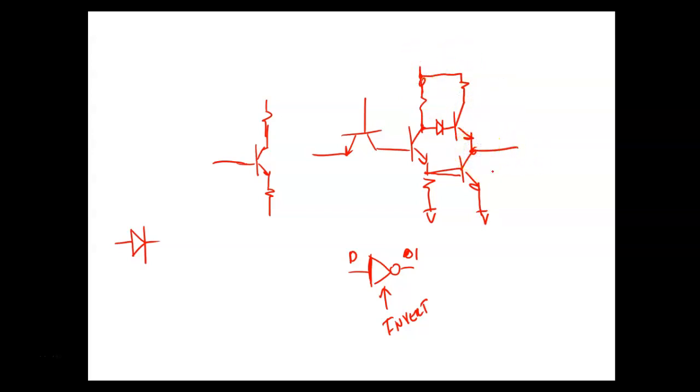And this is where the term sinking and sourcing came into play. So if I come over here and I had a resistor right here, guys. Sorry. So if I was to come in here and put a 1 on, what would happen is this 1 would transfer and it would turn this guy here on, and it would let the 5-volt supply come out. And so this became known as the sourcing transistor because it did what? It sourced the power.